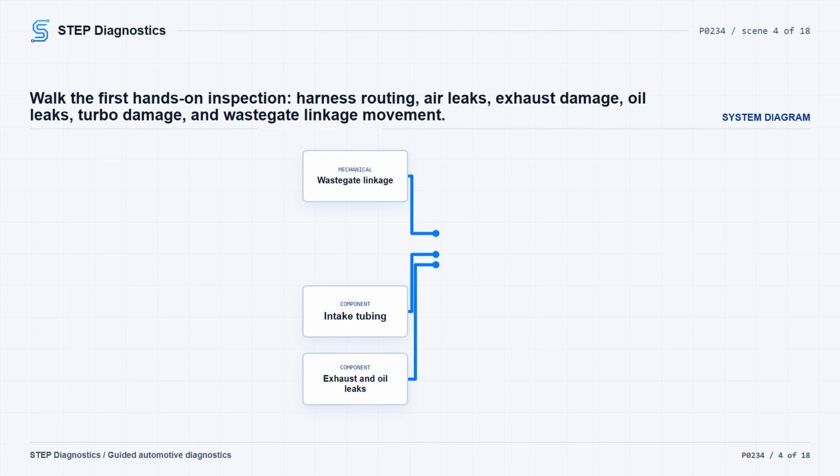Look at the wastegate and bypass control harness routing and connections, intake tubing and intake manifold leaks, electrical connections, exhaust leaks or damage, turbocharger oil leaks, restricted or damaged oil return tubes, turbocharger damage, missing or disconnected wastegate linkage or retainers, and the wastegate motor linkage adjustment and assembly. Move the wastegate linkage with slow, steady pressure toward the motor and then away from it. If you find a concern, repair it as needed, clear the PCM DTCs, and rerun the self-test.